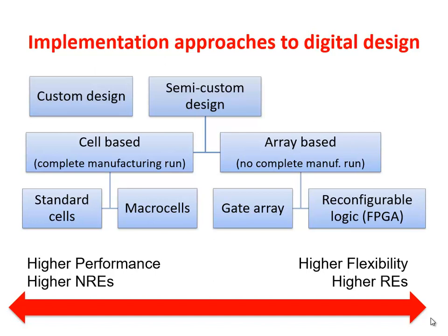Okay, because of course, if you have larger number of chips, then you're interested in having small recurring expenses, so you tend to move in that direction. And if you expect to sell a very small number of chips, then you can have smaller costs if you move in this direction. Because in that case, you want to go away from the high non-recurring expenses. Okay?